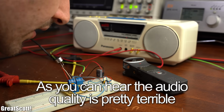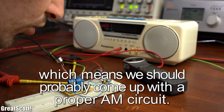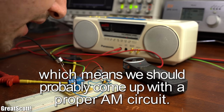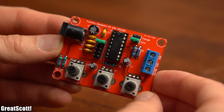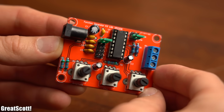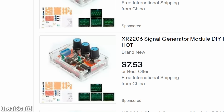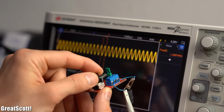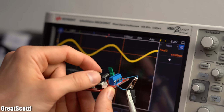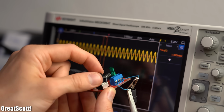And here's how my transmitted voice sounds like. As you can hear, the audio quality is pretty terrible, which means we should probably come up with a proper AM circuit. The simplest solution I found for this was this function generator kit based around the XR2206 IC. You can get such a kit for around $8, and on its outputs it can create a sine voltage with an adjustable frequency that is perfect for our AM signal.